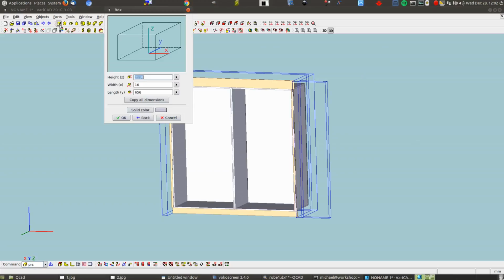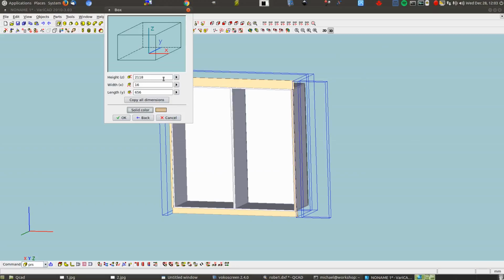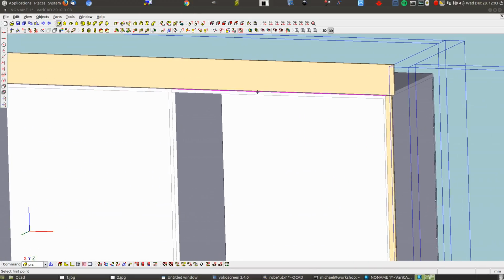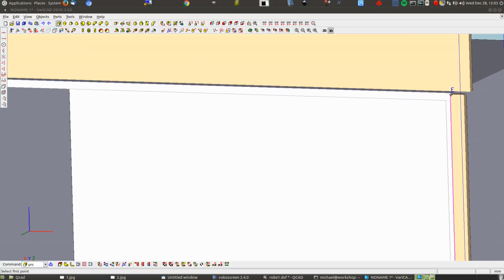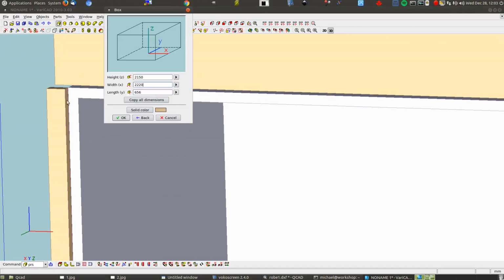The doors have to be face colour. Let's do that. The height was 2150, but again we could measure it off the drawing if we wanted to. I know that it's 2150. The width gets more interesting. It has to be, I use between 3D points. I know it's 2220 because that's what the carcasses were, but we should get the same number just to demonstrate how that can be done. Now, if we have 4 doors, then we'll have 5 spaces. So what we have to do is take away one of the spaces so we can divide up the distance by 4 equally. So 4 spaces and 4 doors in our number.